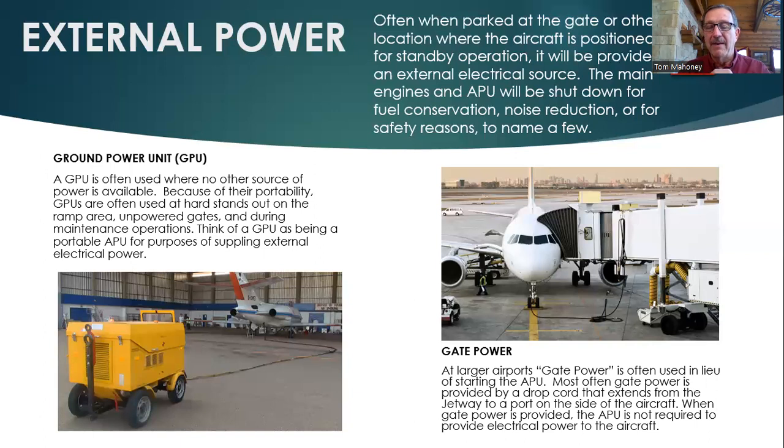Voila, we're all happy. And we would then, before we push the aircraft, start the APU. Then they can pull the ground power, and they would push us off the gate. At that point in time, we'd use the pneumatic air from the APU to start each of the main engines, and we're back on the road again. That's kind of the sequence of events that happens in the airline business for getting the aircraft powered up, keeping it powered up as you come into the gate and at the gate and pushing off.